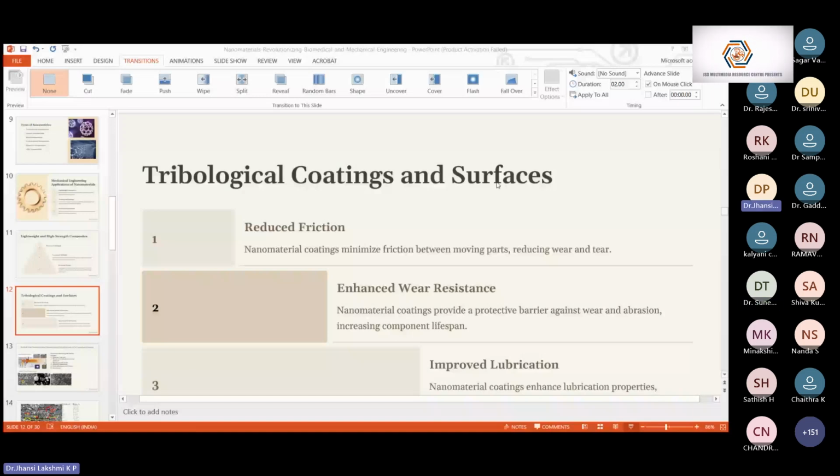It is observed that for a 90 degree angle of impingement, the failure of material is seen in a brittle manner. At higher temperature, the material will fail in a ductile nature. Even at higher temperatures, at 800 and 900 degrees, the coating was strong. The failure of coating was not seen. At higher temperatures, the coating failure is seen as smearing action. These coatings behaved like a ductile material at higher temperatures.